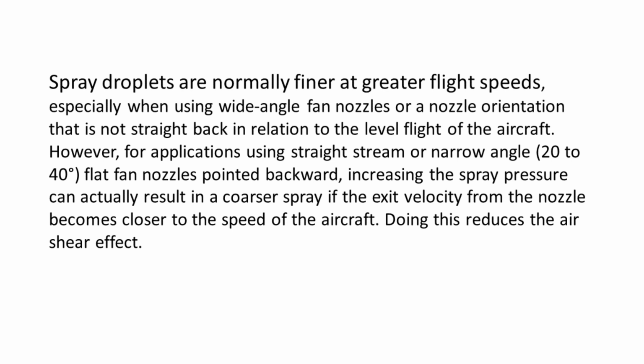However, for applications using straight stream or narrow angle, 20 to 40 degrees, flat fan nozzles pointed backward, increasing the spray pressure can actually result in a coarser spray if the exit velocity from the nozzle becomes closer to the speed of the aircraft. Doing this reduces the air shear effect.